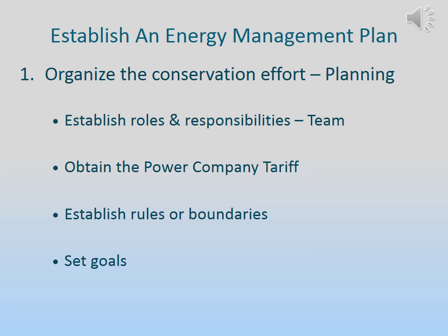We have to get a copy of our power company tariff. We have to understand the tariff because we can look at desktop savings just by understanding the tariff. Sometimes tariffs have time of day rates. That is easy to evaluate using a desktop evaluation. Ask ourselves, is there anything we are doing in the plant where we can change the time of day it is done? We should really understand the tariff as it describes how we are being billed. The tariff has some technical language such as power factor, and that is language we may want to have clarified to understand better.